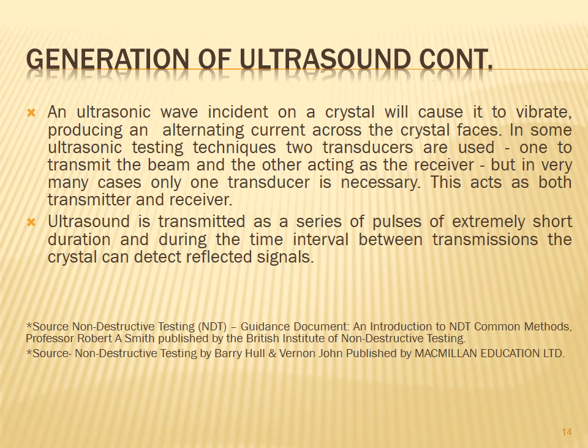In some ultrasonic testing techniques, two transducers are used, one to transmit the beam and the other acting as the receiver. But in very many cases, only one transducer is necessary. This acts as both transmitter and receiver. Ultrasound is transmitted as a series of pulses of extremely short duration, and during the time interval between the transmissions, the crystal can detect reflected signals.